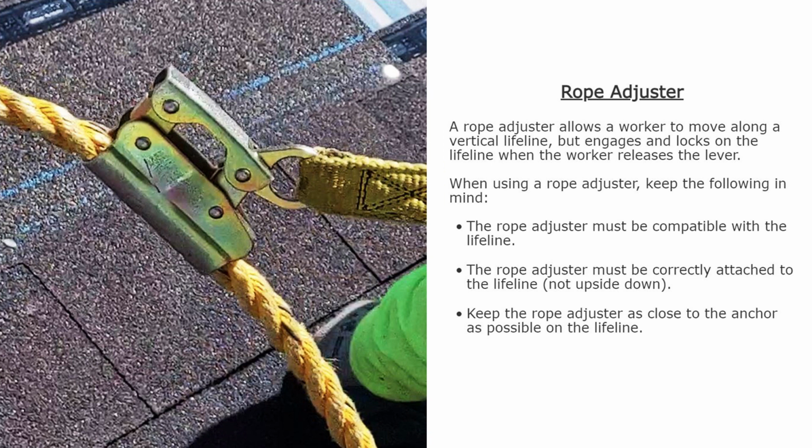Rope adjuster. A rope adjuster allows a worker to move along a vertical lifeline, but engages and locks on the lifeline when the worker releases the lever. When using a rope adjuster, keep the following in mind. The rope adjuster must be compatible with the lifeline. The rope adjuster must be correctly attached to the lifeline, not upside down. Keep the rope adjuster as close to the anchor as possible on the lifeline.